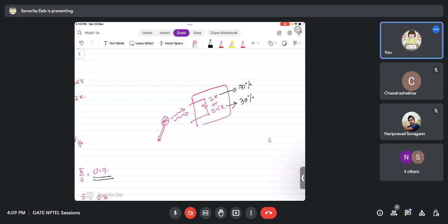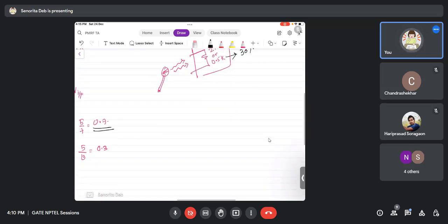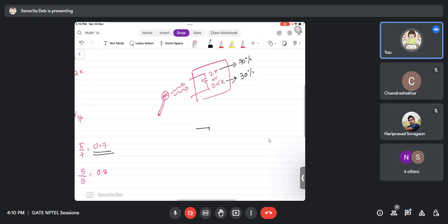I will put an amplifier which has an input impedance of 2k, so that the maximum part of my microphone signal is received. If I receive only 30% of the microphone signal, then what I reproduce will be further degraded. I actually wanted 100% of my signal, but when will I receive 100%? When the input impedance of the amplifier is infinite, right? Infinite means what?